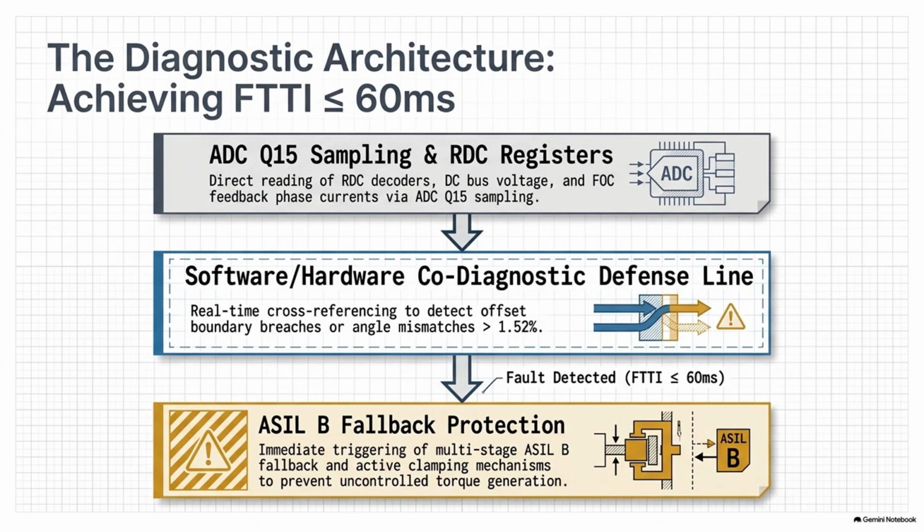Well, that requires real-time offset checking. The software runs a continuous background algorithm while you drive. And one of the primary methods is monitoring the D-axis parasitic power loss during steady speeds. Okay, back to our D-axis and q-axis. The D-axis builds the magnetic flux, the q-axis applies the torque. Right. So when you are driving at a steady 65 miles per hour on a flat, unloaded highway, the motor control dynamics are very stable. In a perfectly aligned, healthy motor, the unloaded D-axis current should perfectly match the computer's theoretical commands. It should be relatively constant.